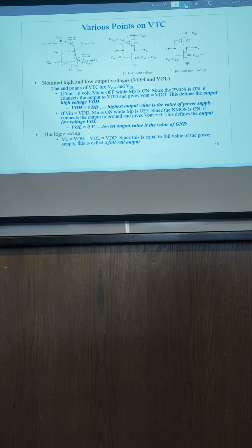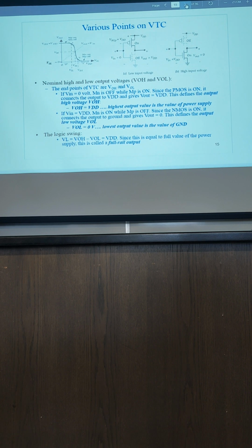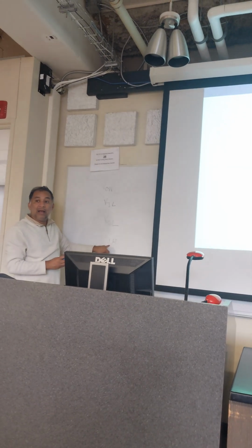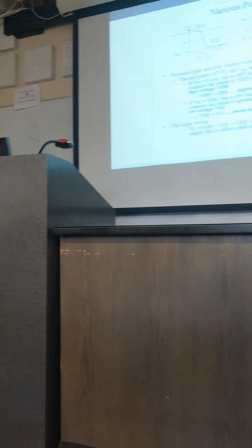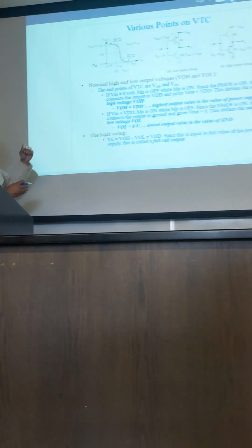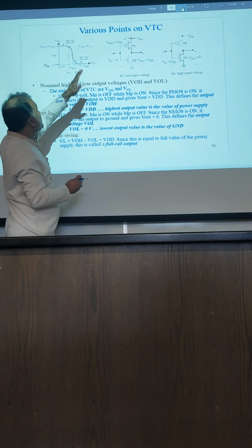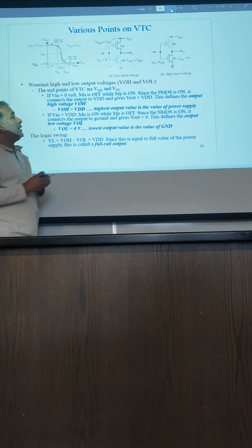The fourth point of interest is then VIH, V input high. What is the minimum voltage above which input should be considered as a high input, for which output should be low? And then we introduce a transition point, the midpoint of the voltage.